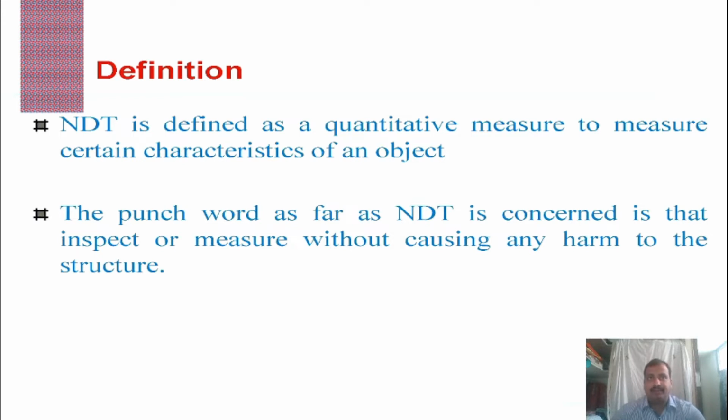Now, we can say that the range of properties that can be assessed using these NDT techniques or partial NDT techniques is quite large and includes such fundamental parameters as density, elastic modulus, strength, as well as surface hardness, surface absorption, and reinforcement location, size, and distance from the surface. So these we can evaluate by using NDT techniques.